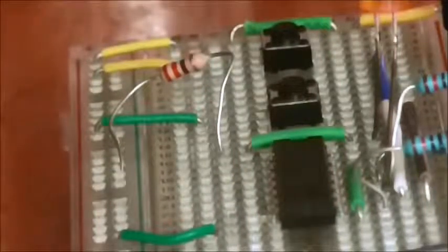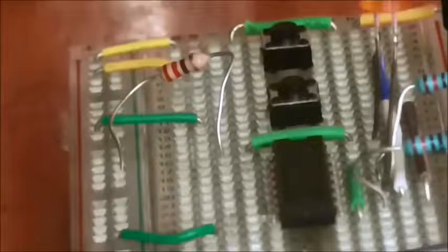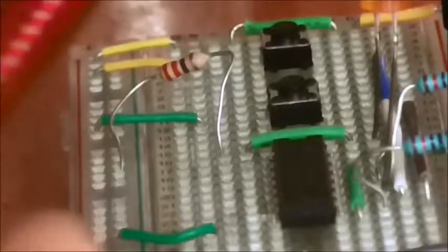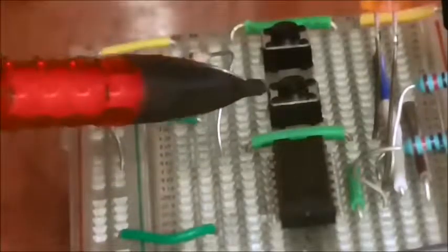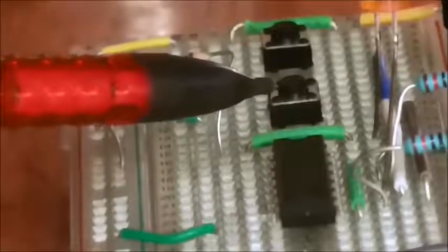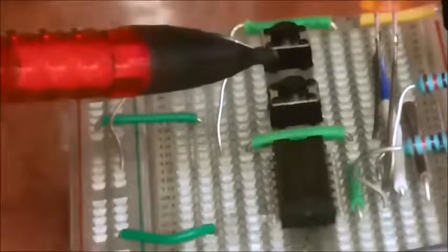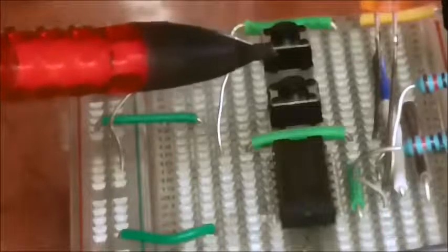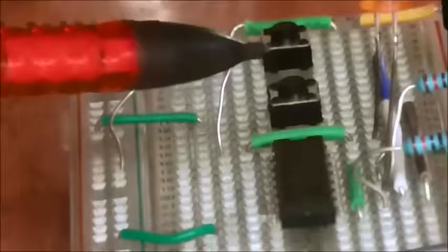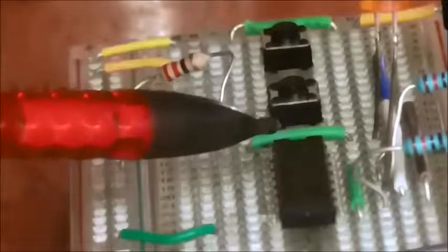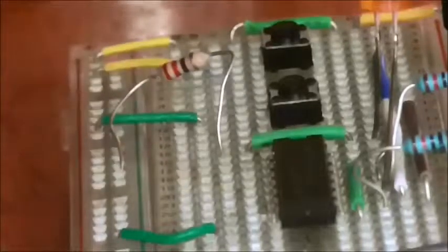Well, let's have a quick look at what's going on here. Now, you'll remember me going on about pull-down resistors, and here I put two pull-down resistors in to make sure the first NAND gate is reliably low when I want it to be. And as we know, when a NAND gate is low in any input, the output will be high. The output of a NAND gate will only be low when both inputs are high.